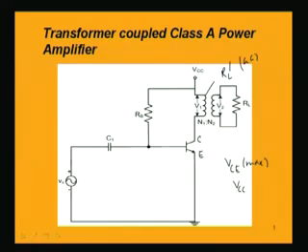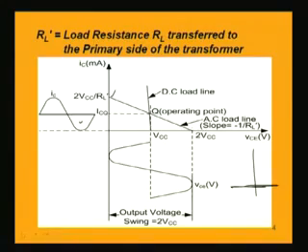It will be aiding the voltage VCC so that it prevents the fall or collapse of the collector current. It is due to Lenz's law. It will not allow the collector current to fall, opposing the very cause behind the fall, and it will add a voltage equal to VCC. That is why the total voltage at that point, when the collector current goes down to the valley, will be 2 times VCC.